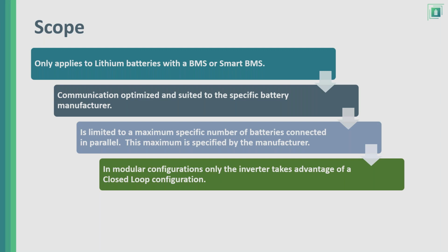So now not only the inverter, but the charge controllers will know as well what parameters are required to charge, or up to which point I can discharge this battery. One of the benefits of the all-in-one system is that the information being exchanged between the batteries and the system will apply to all the components of the system. It will not happen with the modular systems, because they're just not part of it.